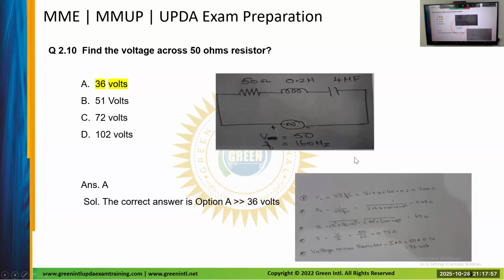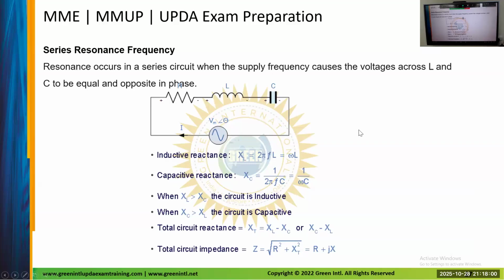In the resonance circuit, the voltage is constant and we change the frequency. If we change the frequency, what will happen? The behavior changes, because L and C depend upon the frequency. That's why the behavior entirely changes. That is related to the resonance circuit, which is used in communication. Simply, in the radio or any communication circuit, either receiver or transmitter, in both cases the resonance circuit plays a vital role.